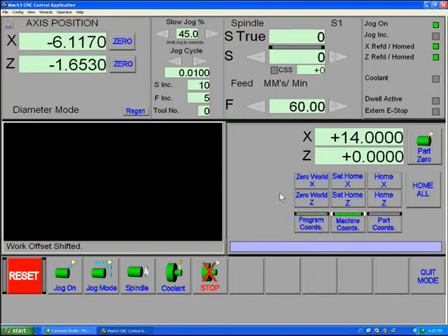Machine coordinates are available to you, but unless you're using home switches and you understand the various offset systems, you would normally leave it on program coordinates. The machine coordinates button can be handy for debugging or wrapping your mind around the concepts involved. We won't go there, though, at the moment.